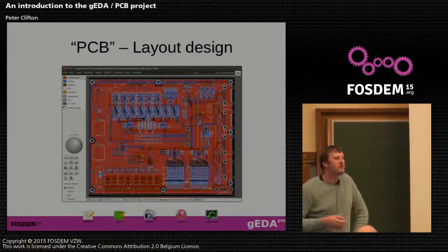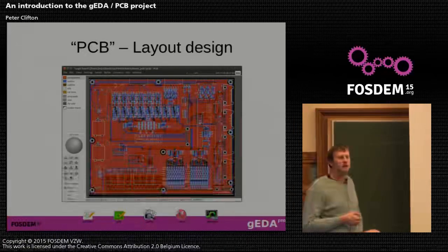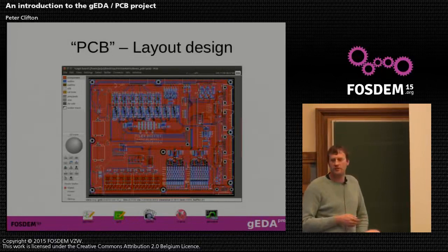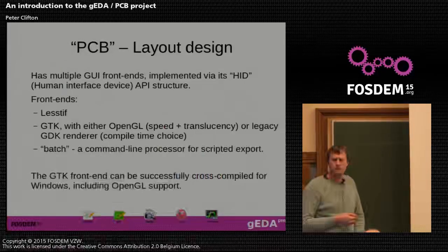PCB has multiple front ends. It's a separate code base to gEDA and has a completely different internal structure. Front ends we've got a Lesstif front end, which was written by DJ Delorie and works upon the older X11 based front ends that use the Motif toolkit, I think, and probably before that the Athena widgets toolkit, and is a very traditional sort of Unix-y, high performance, no frills, no GTK front end, and a lot of people quite like that.